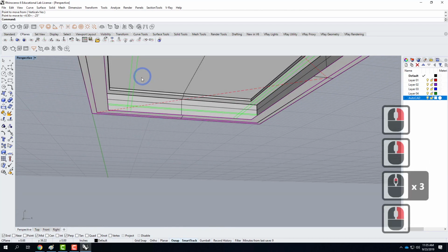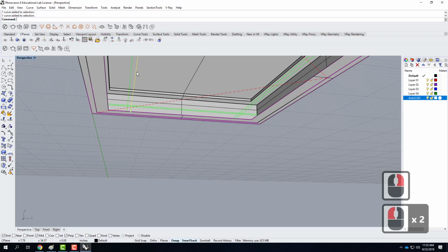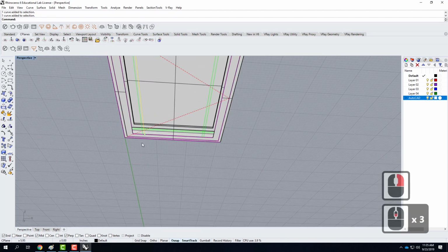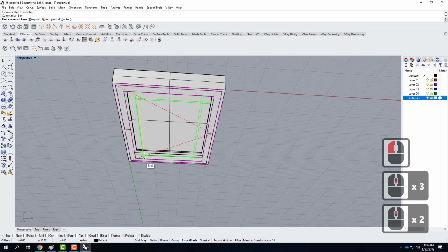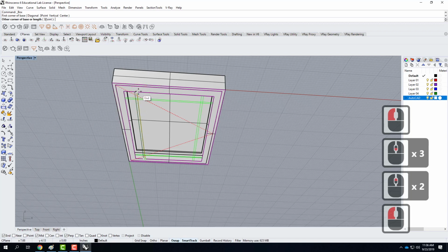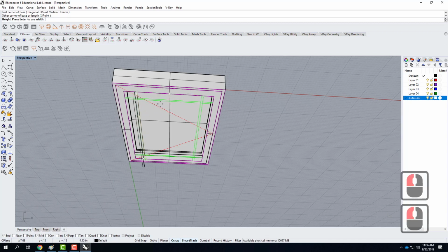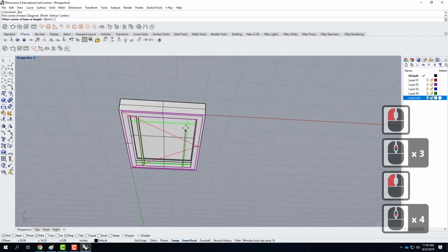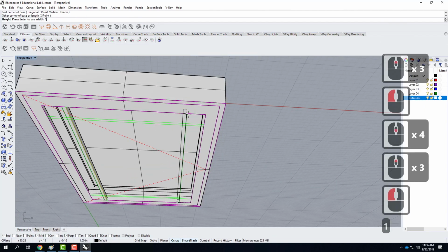There were these other pieces, these here, that were dividing up what the grids look like on the window. So if I wanted those grids, I could go ahead and create little mullions for those pieces. So let me go ahead and I'll use the box corner to corner to do that. And I'll just trace over. I could use a split. I could have done that. But in this case, I'm just using a box. And I need my thickness of my mullions, oh, I don't know, how about an inch? Same thing, box over here. We'll go from there to there, and we'll say maybe an inch.